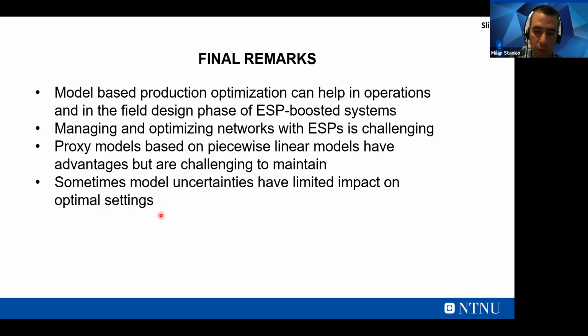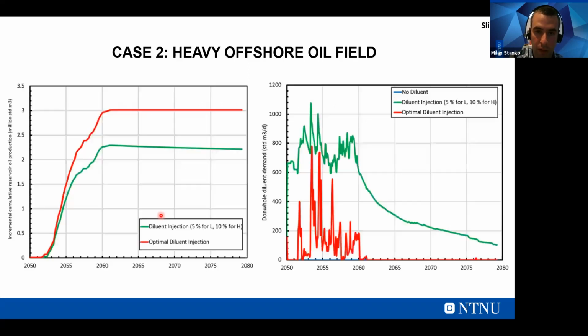Even if the model is not that good, you can still get useful inputs from it, because you can see that the uncertainty doesn't change the optimal values that much. You might still have a significant change in the rate of oil, for example, but not on the optimal settings, on the diluent injection and, for example, the frequency.